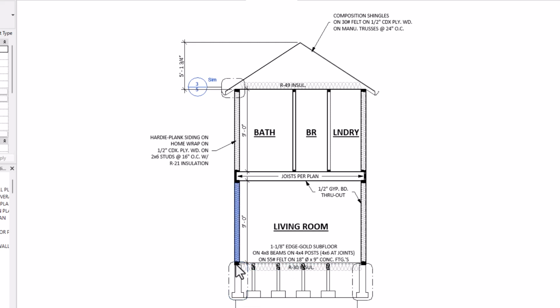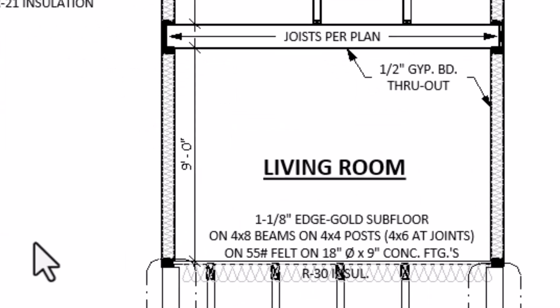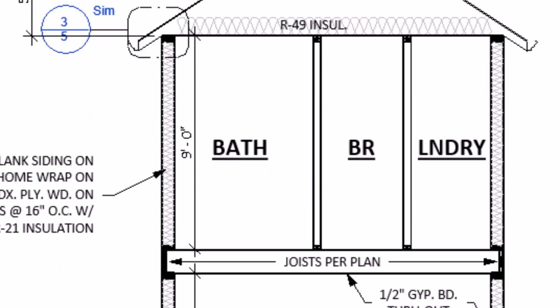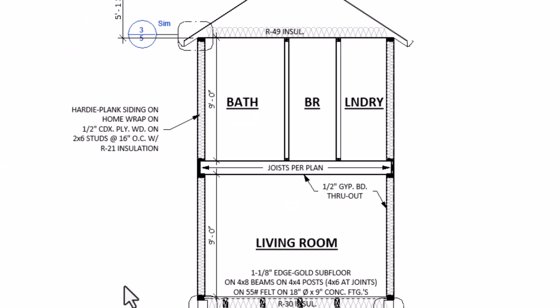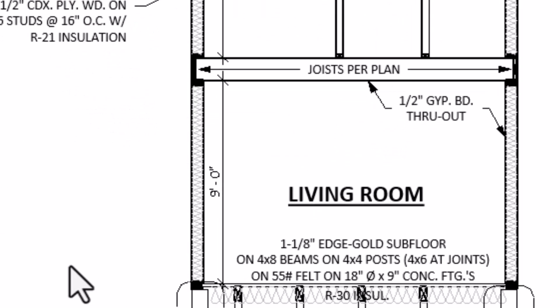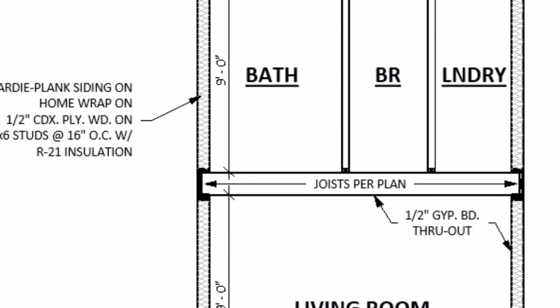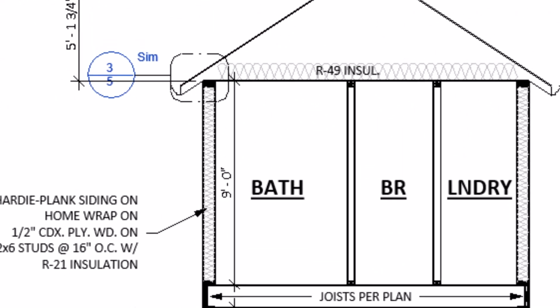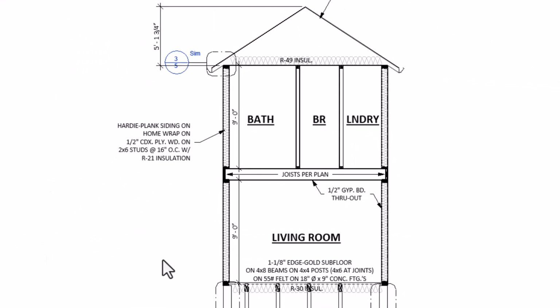In the first floor diaphragm we define as 0. In this building you can see that the first floor walls are 9 feet tall and the second floor walls are 9 feet tall, and we assume that the floor system is more or less a foot tall. So if we add 9 feet plus 1 foot for the floor plus another 9 feet, that gives us a total of 19 feet to the top of the top plate of the second floor wall.